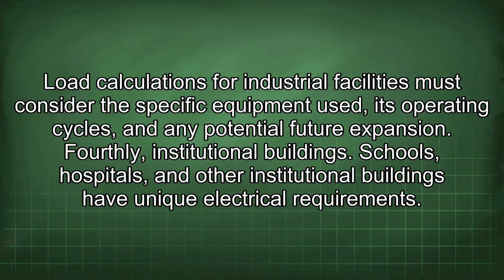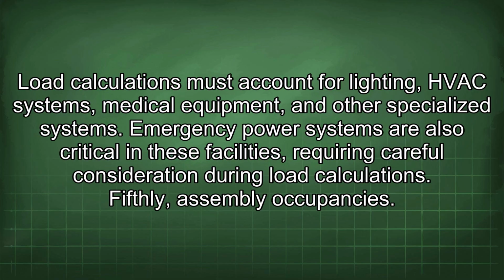Fourthly, institutional buildings. Schools, hospitals, and other institutional buildings have unique electrical requirements. Load calculations must account for lighting, HVAC systems, medical equipment, and other specialized systems. Emergency power systems are also critical in these facilities, requiring careful consideration during load calculations.